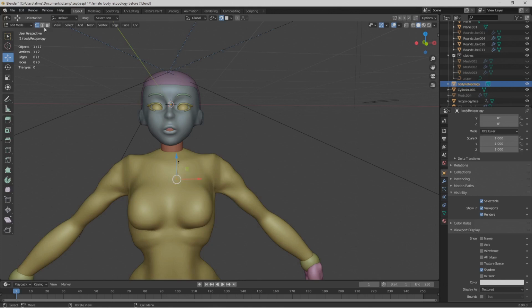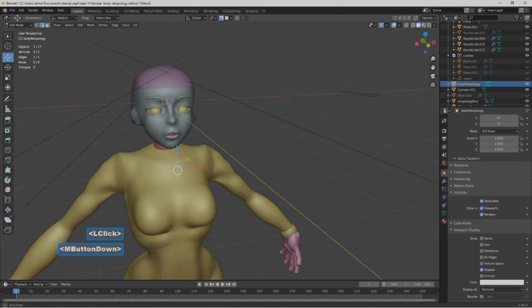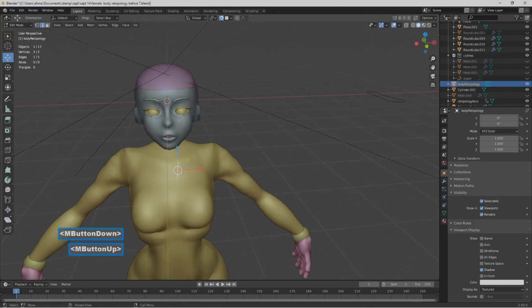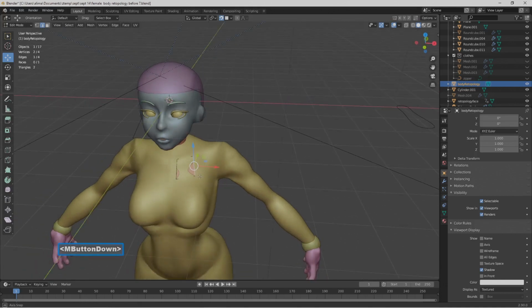Now that we have that, I'm going to go to the upper left, go to edge select. Now select this edge. So I'm holding the middle mouse button to rotate. Now I'm going to hold control. Then I'm going to right click. Now when I right clicked, right, I let go of control. We can see that the geometry came out to here, right? Not only did it come out to the side, it also angled itself up, which is extremely useful.